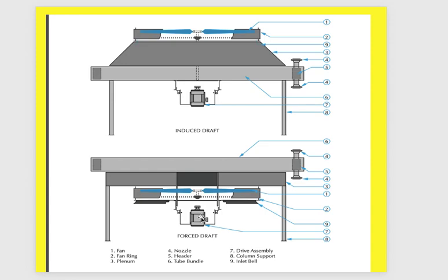The vane motor here, as we can see. Okay, this is element number 4. The vane motor provides mechanical power to rotate the vane, and this electrical motor is usually explosion proof for sure and designed for continuous operation. It can be fixed speed or variable speed. Variable speed is to control the temperature more, okay, or it can be fixed speed.